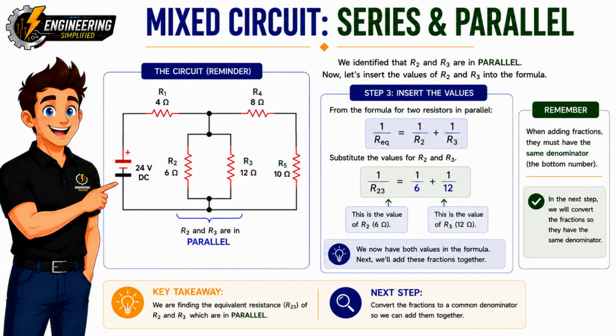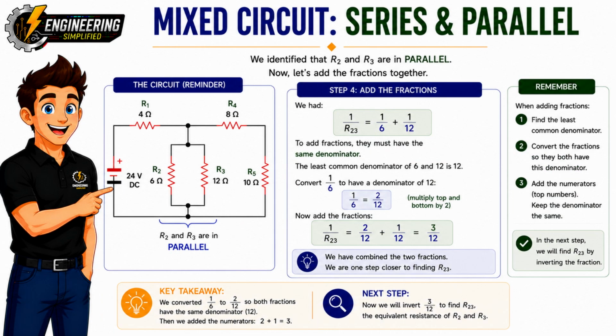This formula gives us one new resistor that behaves exactly the same as the two original resistors. Once we've found that equivalent resistance, we can replace R2 and R3 with a single resistor, making the rest of the circuit much simpler to analyze. Remember, this formula is only used because R2 and R3 share the same two connection points, which means they are connected in parallel. In the next step, we'll substitute the actual resistor values into the formula and calculate the equivalent resistance of this parallel branch.